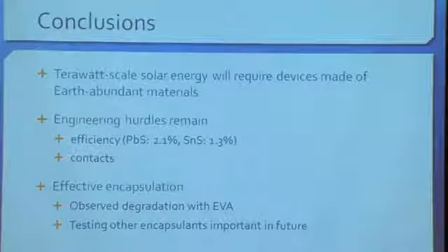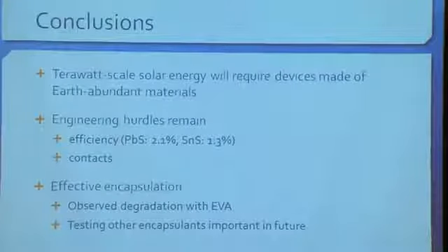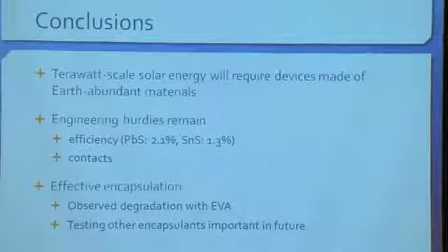And we think that the method that we came up with of testing materials in the environmental chamber will be useful in the future, and ideally you could test different encapsulants and see how well the IV curves stay after the environmental testing. So we'd like to thank several people for helping with our project, in particular Andy at Fraunhofer, who's actually here today.